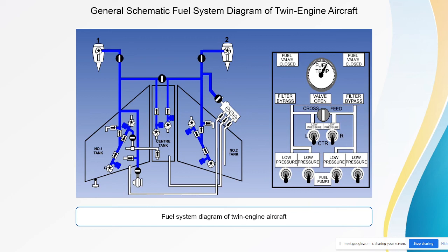Normally, try to do a schematic diagram like this, and explain how the system flows. Because later on you are talking more on the float switch, the float valve, but the main thing is how the system flows. Explain that one, then only go to certain areas, like what is the pump function. Overall, this is the type that you guys go in normally if asked to do a system.